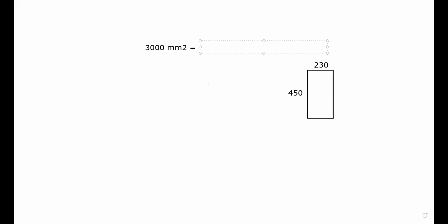But now what dia are you going with? As one of the students over here said, 25 mm dia rods. So for 25 mm, calculate the area of one rod. Please calculate what is the area of one rod of 25 mm. That is what we used to do in RCC, right? I'm not asking any new question. So pi by 4 into d square. How much are you going to get? 491.